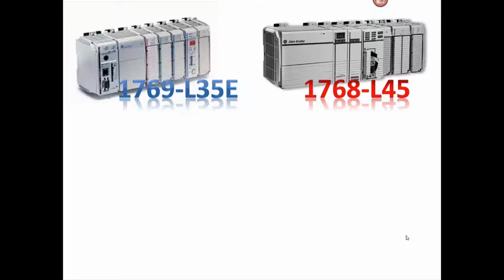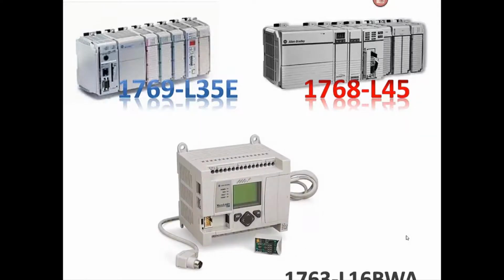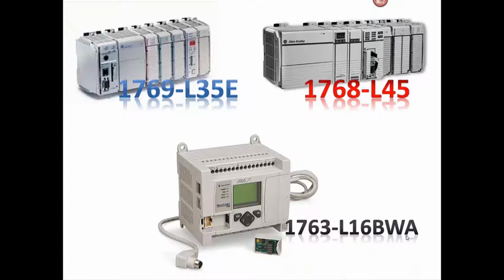So these are the two main players in what we're going to do in this lab. However, to make it interesting, we threw in something from an older platform. I have a 1763-L16BWA, which is a MicroLogix 1100 that uses 115 volts for power and has DC inputs, and I don't know if it's relay outputs or DC outputs. I don't actually have anything wired up to the inputs and outputs of this controller. I'm just using this to demonstrate how to communicate from the L35E or L45 to the MicroLogix 1100.